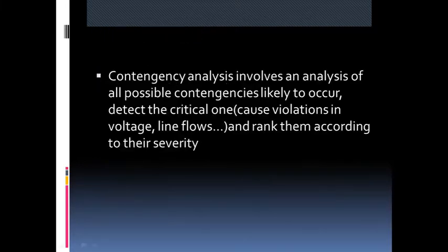Contingency analysis involves an analysis of all possible contingencies likely to occur, detecting the critical ones that cause violations in the voltage and line flows, which may be active power, reactive power, and even current, and ranking them according to severity.